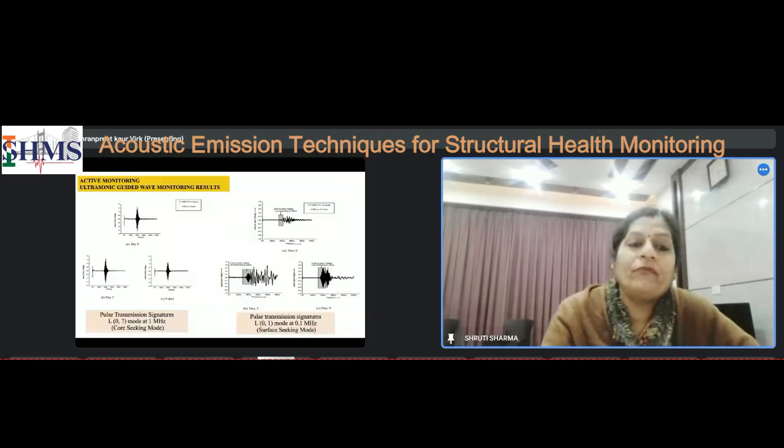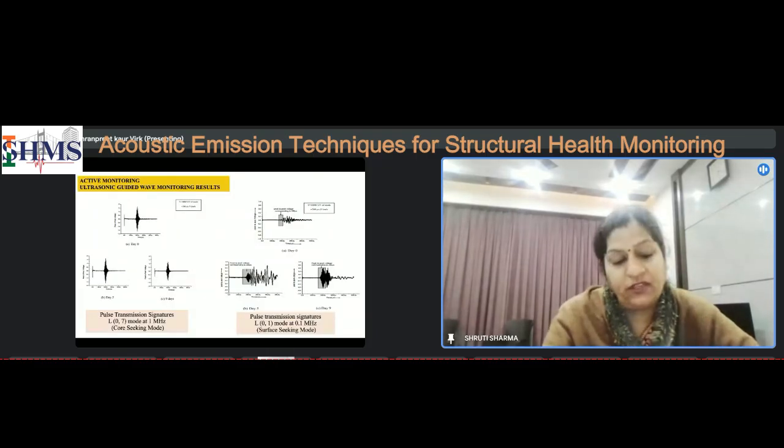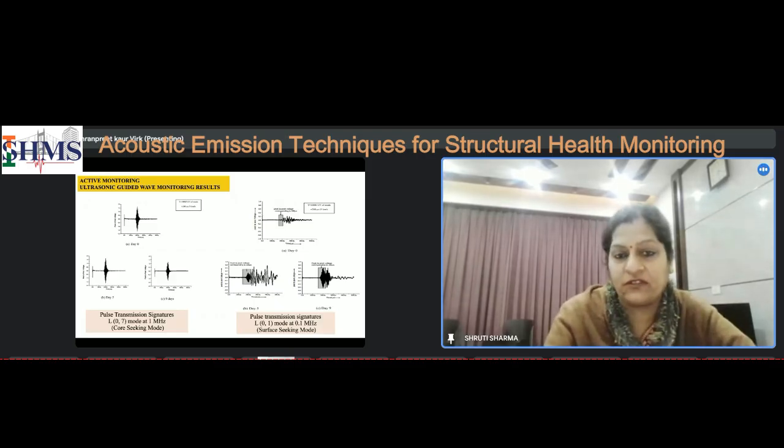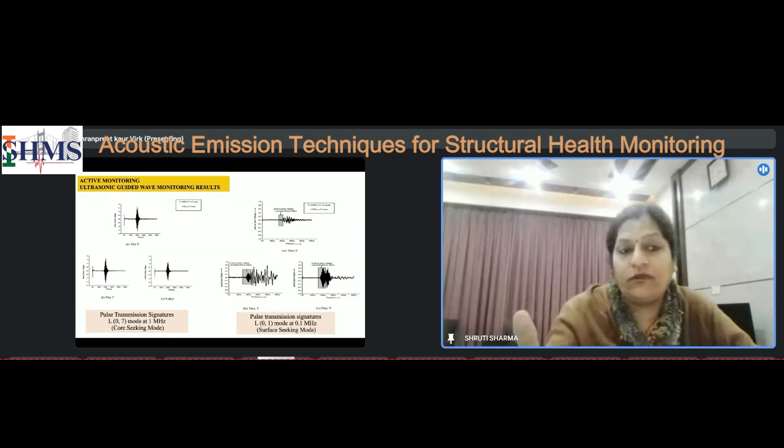Next slide, please. So when various frequencies were used to detect the damage inside the corroding rebar, if you see on the left hand side, the signals did not change even after 9 days of accelerated corrosion. Similarly, on the right hand side, the box shows there is some signal which is rising, but not to that extent until the fifth or sixth day. So initially, for 1 to 9 days, we were trying to monitor the beam subjected to accelerated corrosion. We found out that guided waves worked very nicely in the later stages when the corrosion had exceeded a particular level, but not on the initial stage.